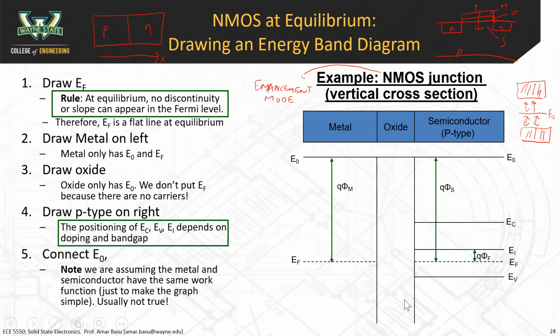In this type of situation, this is the electron affinity there. We think about what the holes are doing in the substrate here. Remember that in a p-type substrate, there's a lot of holes and very few electrons. So we're going to be more interested in what the holes are doing. And you can see that the holes are down here. The EF is closer to EV, so there's a lot of holes. There's very few electrons. There's no bending of the diagram, so those holes aren't really going anywhere.